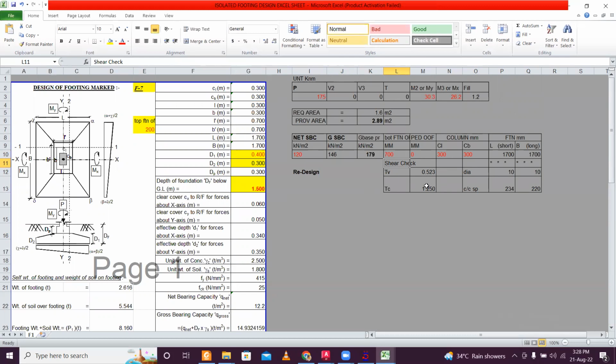It's coming close on this value and all. Okay, this is showing redesign. So 750, redesign. 800, redesign. 850, okay. So at 850, it is okay. That is 2000 into 2000. If it's 2 meter, multiplying it by 3.28, it is around 6.6 feet, the footing size. So it's around 2 meter.